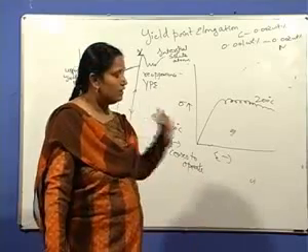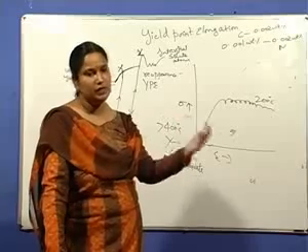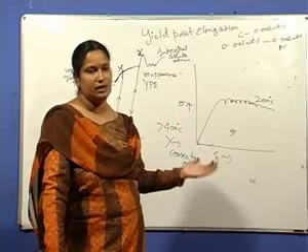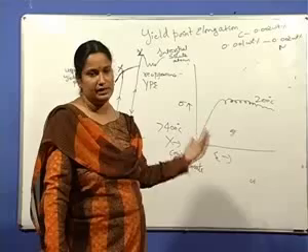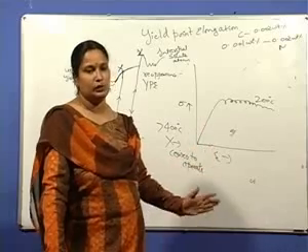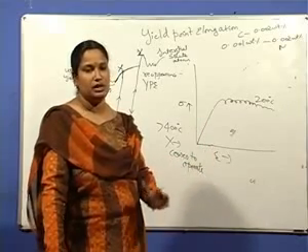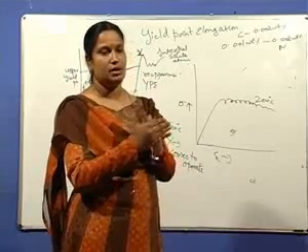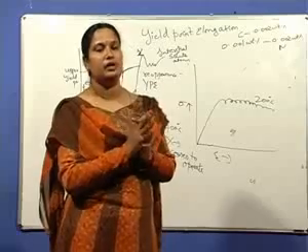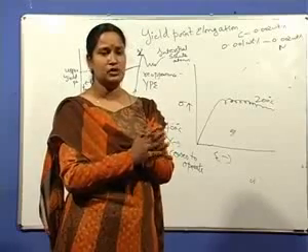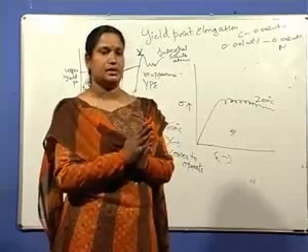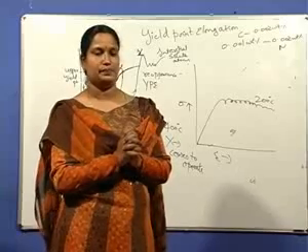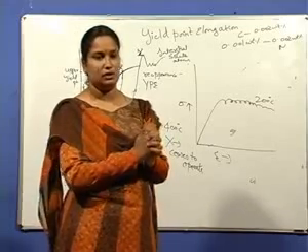And if you leave that material even after temper rolling or skin pass rolling, again it reappears at slightly higher stress. So immediately you have to form that part after giving this temper rolling or skin pass rolling. Now you have to answer all these questions by the end of this module, because this is what we have discussed about all these topics. So try to answer all these questions,